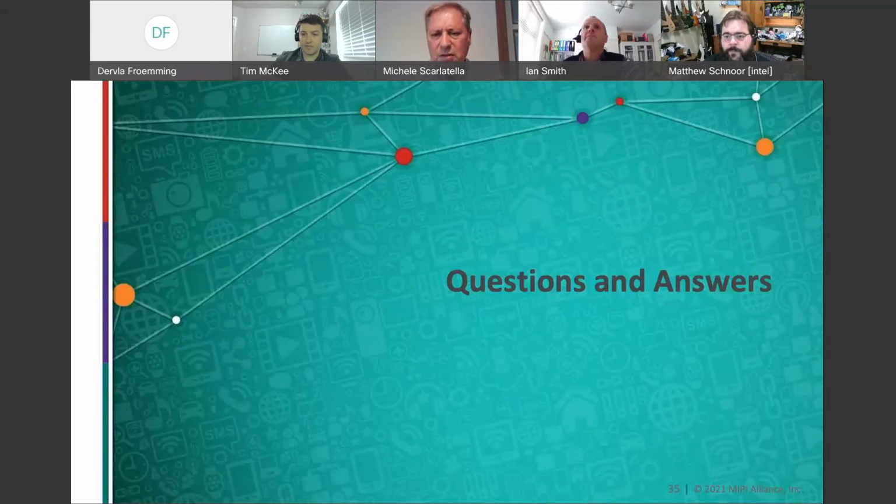Clock stretching is only allowed in very specific cases. We found that it's really seldom used. Most of the time, the controller will run at a speed which is compatible with I2C. It will only go into I3C mode if it's sure that, as I showed in the transaction, you only switch to I3C mode where you're sure that I2C devices are not active on the bus. Otherwise, you will run at a speed that is compatible with I2C.